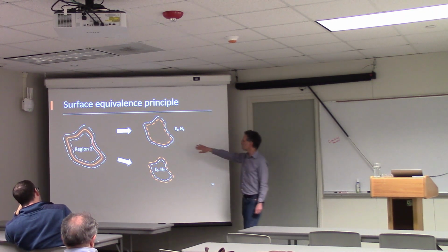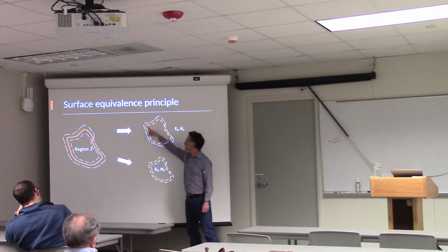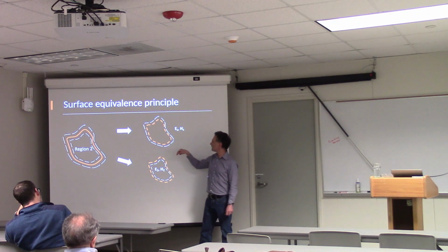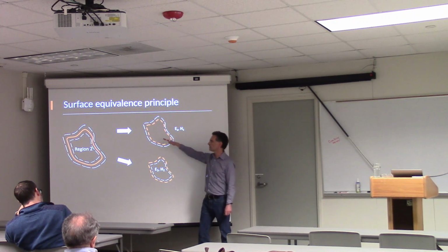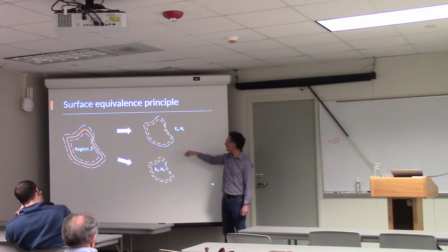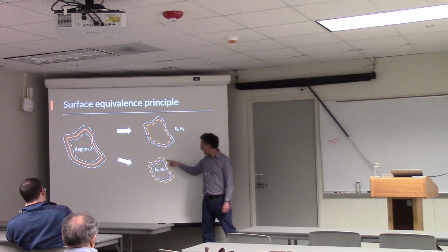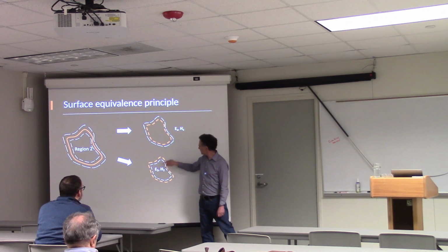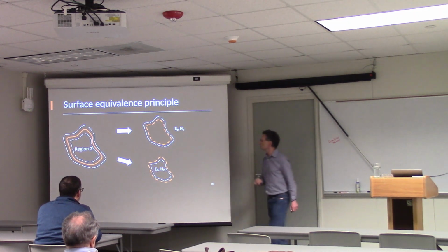The two-dimensional fields are going to wind up being currents, so magnetic and electric currents. They are fictitious. There are no currents really there, which is good if they're going to be magnetic currents. And these currents are the unknowns in the problem, and the currents define the fields in those two regions.